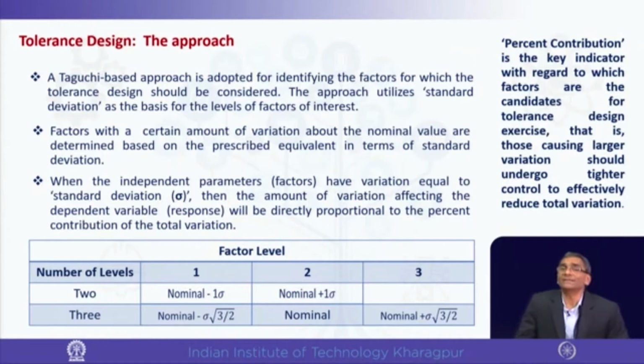Now, to assess the effect of variance, it is not exactly the limit based monitoring, the USL, LSL, upper specification limit, lower specification limit, and tolerance stacking. It is rather to check the effect of variance of the inputs on the final product, the output, and here our purpose is to mitigate that by adjusting or tightening the tolerance more specifically.